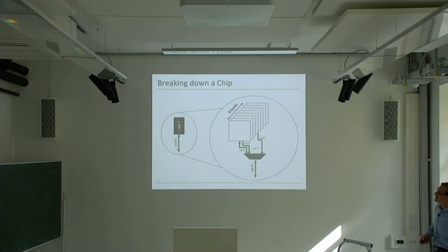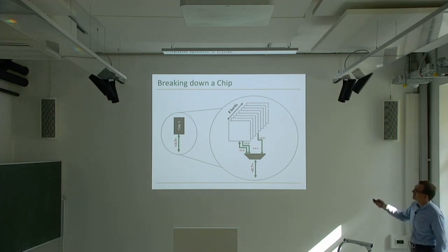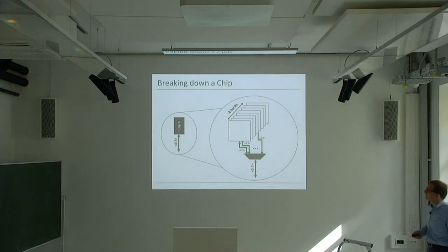Okay, if you go inside, a chip has 8 banks, as we've seen, in this case 8. But these 8 banks each can provide 8 bits of data in a cycle, but they get multiplexed. So only one bank can provide the data in a given cycle, and then you need to multiplex them. But you can overlap the activation latencies clearly across the banks.